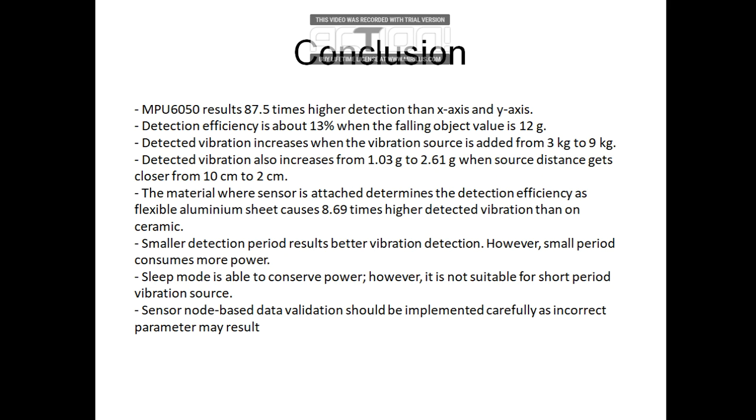Smaller detection period results in better vibration detection even though it consumes more power. And then sleep mode and sensor node data validations are not recommended for vibration detections.